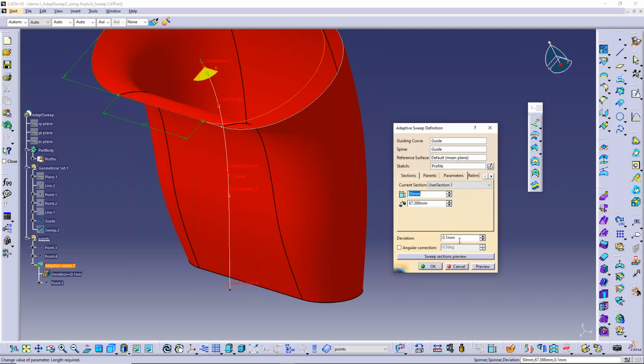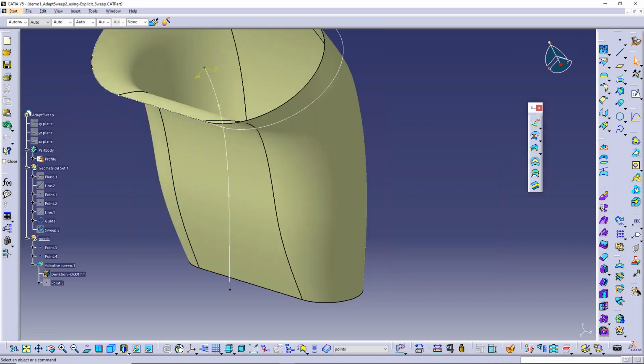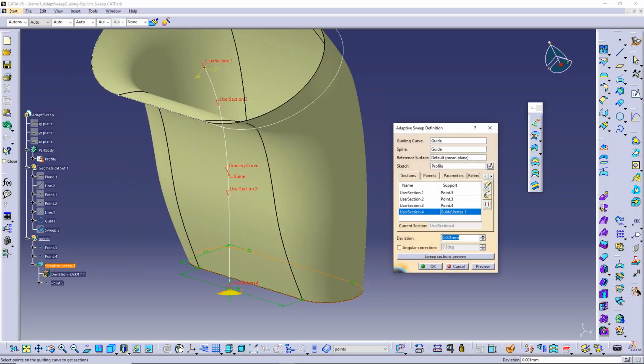You might want to start with a low deviation to help in the progression of the sweep without a lot of bumps. If you ever notice your shape has a lot of bumps or lumps to it, you might be able to come into this deviation field and adjust the values. Usually you can go a little lower and it helps. If you get to a point where the value is not something that can be regenerated, then you don't get output.